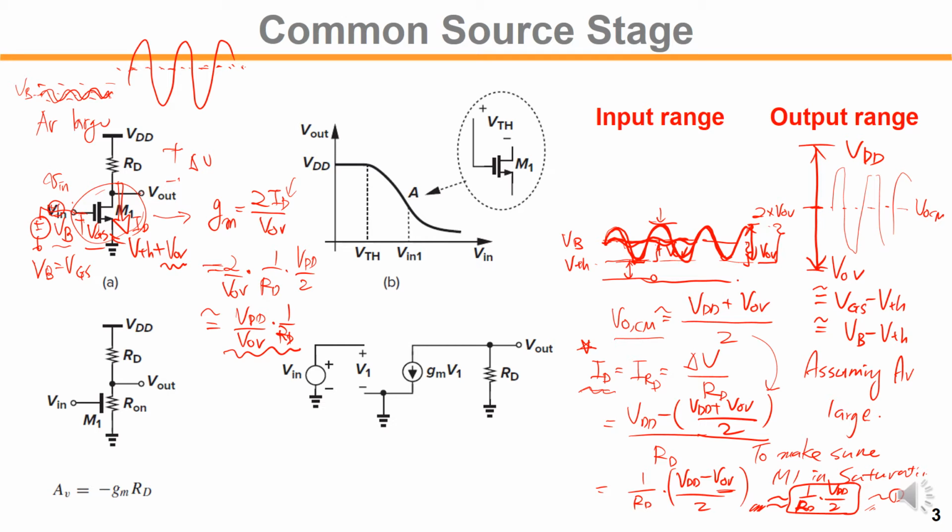So once you determine the topology, the GM, you can design your GM by having a different size of M1. But having a different size will determine the overdrive voltage, and you don't have much freedom to change the current, because to maximize output swing, your desired current level is fixed by equation 1. So that leads us to the GM that we can use for this device.